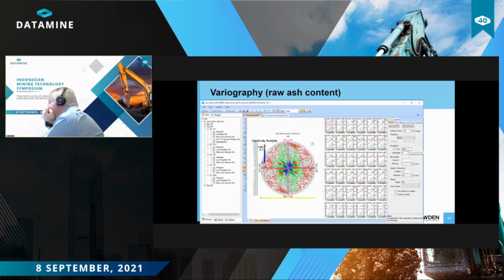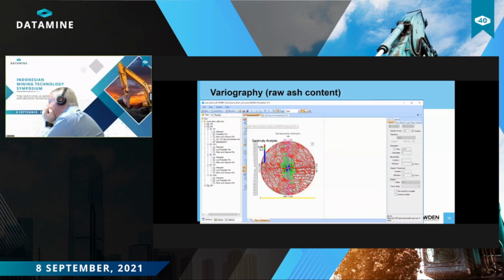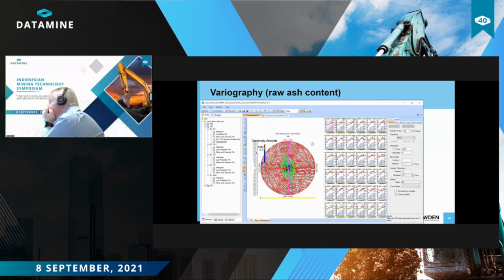We can also change the distance the fan is looking away from the central point by changing the separation distance, let's say to 4,000, and we'll rerun it. We can now toggle up and down the sideband here to zoom in and out on our variogram variability map contour plan. Let's reset that to 2000.